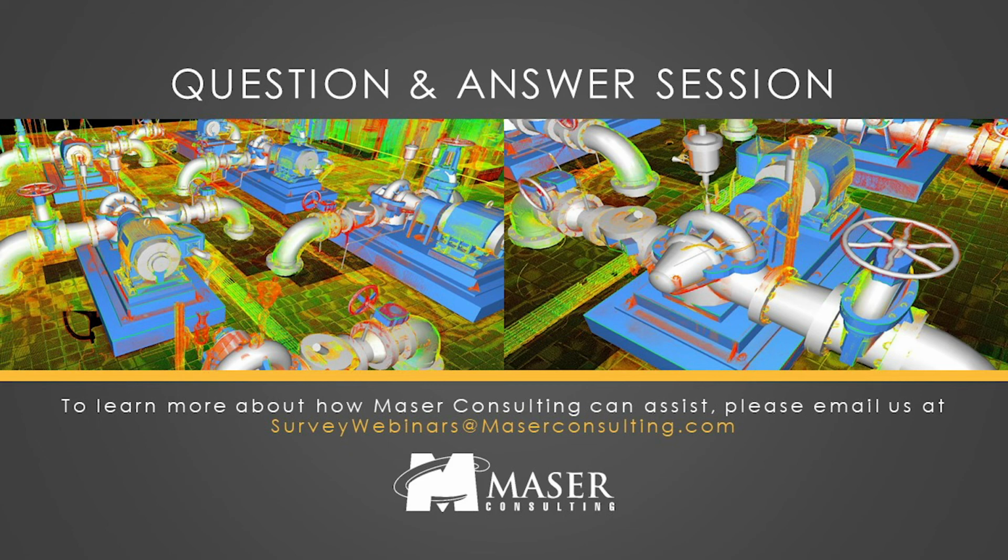So generally, in order to get that volume, to get that surface data, you're going to need to make the surface from the scan. It's not like you can simply take the scan and measure a volume underneath it. You would have to develop a mesh for that first a lot of times. I believe that's the workflow in Cyclone still. So you would develop a mesh based on your point cloud, and then from that mesh you can get the volume data that you need. You could additionally bring that mesh into Civil 3D and others and create a surface in there to get your various data from that mesh.